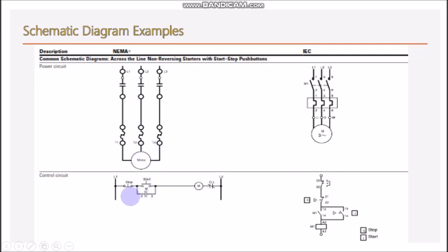Okay, we have here, see, that's a parallel contact, an auxiliary contact for contactor M. Okay, once it is energized, this contact will be closed. Once it is closed, it will make a bypass for the start push button. Why do we need this? Because the push button will go back to normal once I remove my thumb from it, so it will go back again to open.